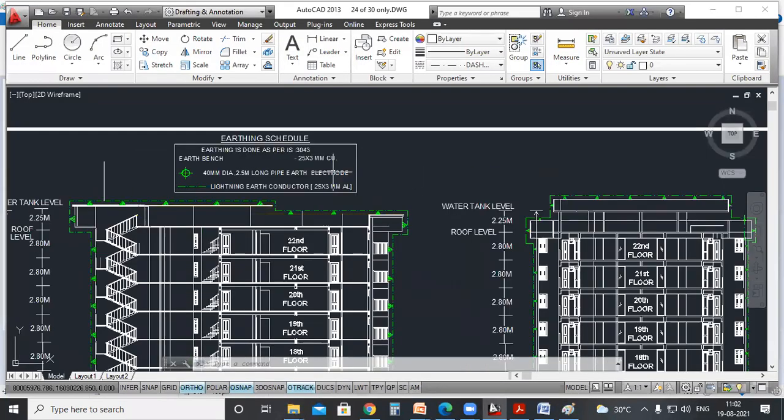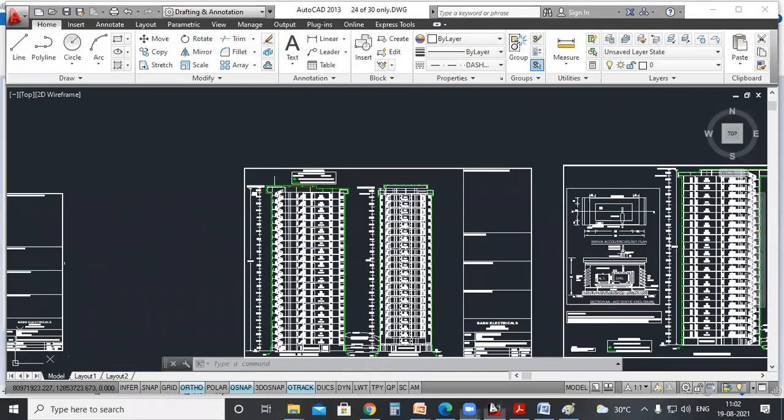So this is actually the building. A separate earthing wire will go to the DB. From where you are asking, a separate earthing wire will go to the DB. Obviously, the DB will have separate earthing. For the surge protective device connected parallel to the incomer, this surge protective device will go to the separate earthing.